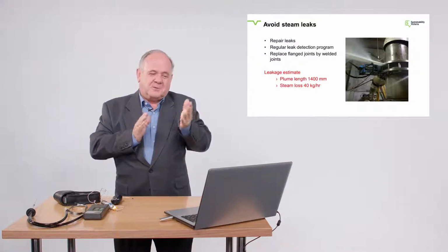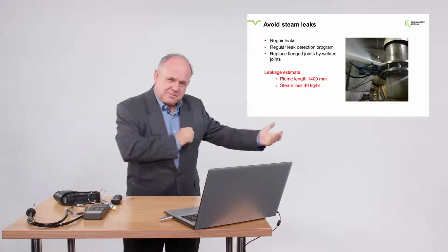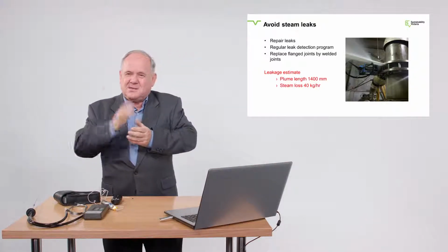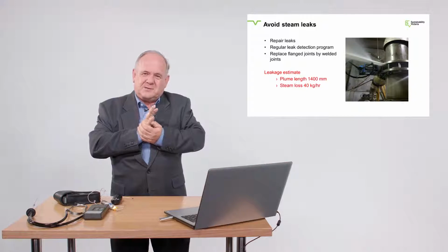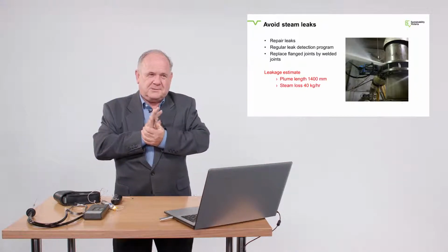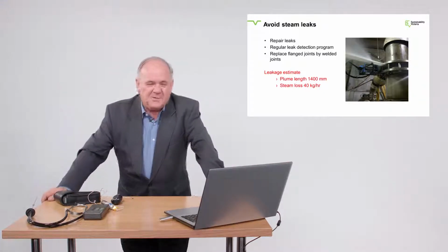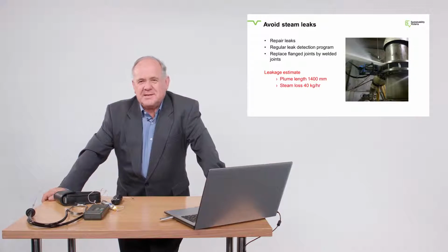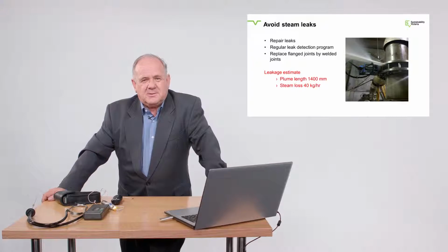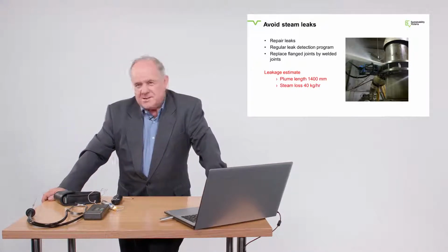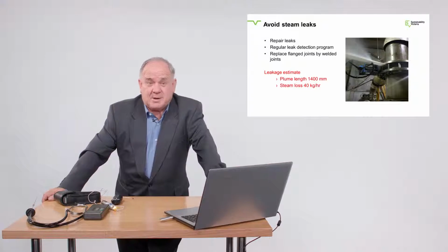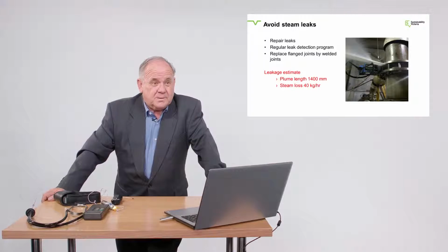A lot of maintenance people don't focus on steam because they're busy keeping machines going and other things. But if you said to him, well, if you fix 2 or 3 of those, that might be your wage. So why don't we fix them? One thing I have noticed in more recent years is that steam leaks are being repaired because they are dangerous. If you walk down, they're very hot. So they won't fix them for energy savings, but they will for occupational health and safety reasons. But you get a double whammy there.